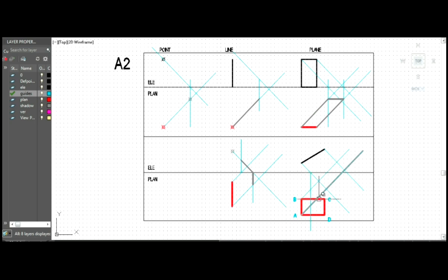Okay. So for the light ray coming in from CD in elevation, we will draw 2 more 45 degree lines for the light rays here from the plan. Okay. So this light ray in the elevation intersects with the ground line before these two lines. So we draw the vertical line down.